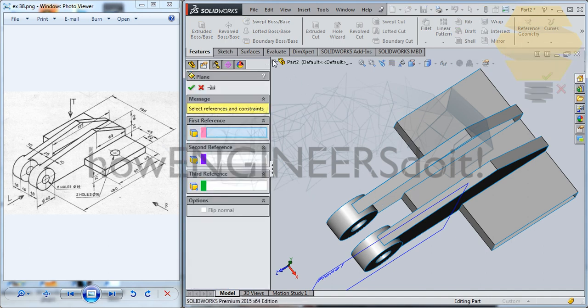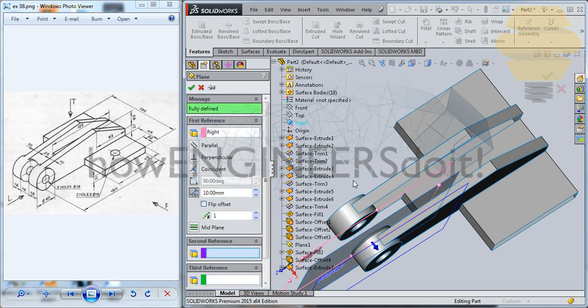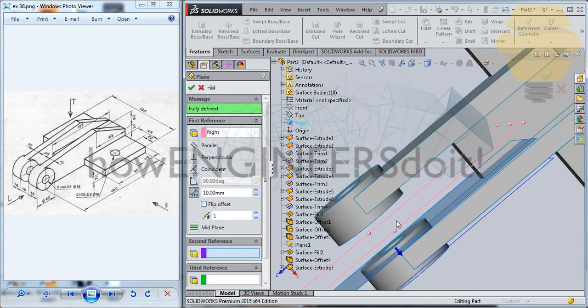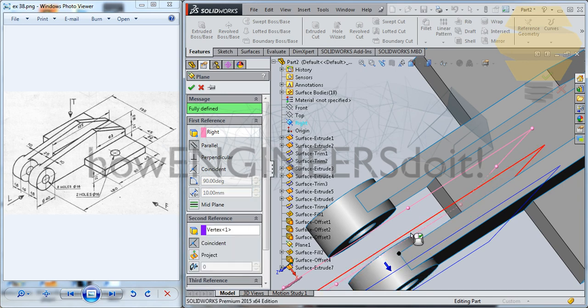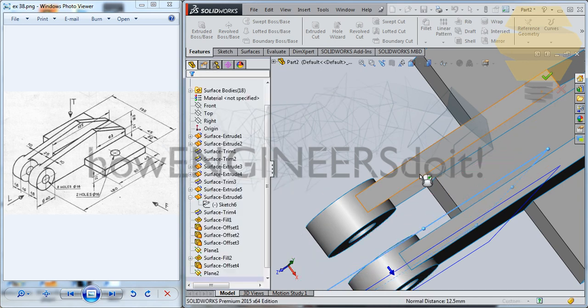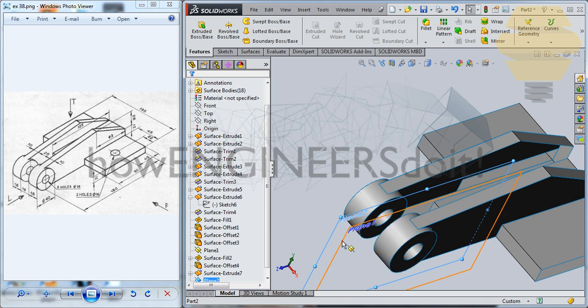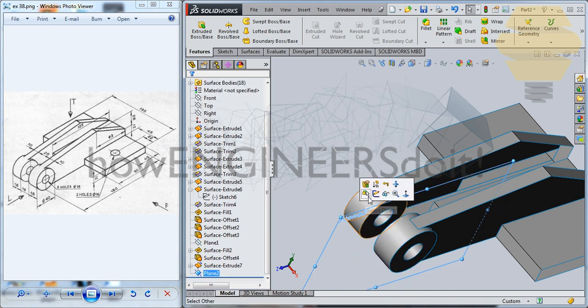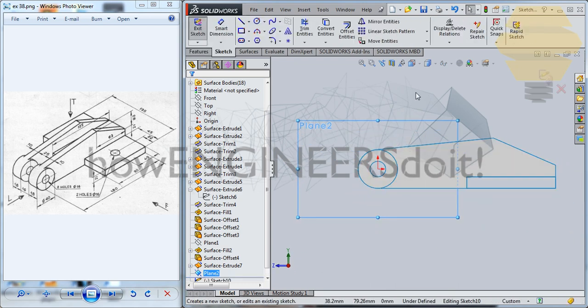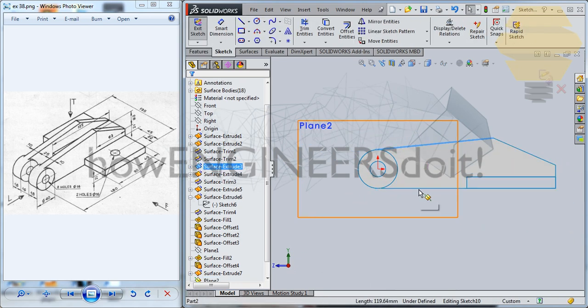Now what we gotta do is go for features and create a plane referencing the right plane at this point, this time, at this point. Go for tick mark. Now let's hide the previous plane so that we don't have room for confusion. Go for that plane there. This time you select this, everything else like before.